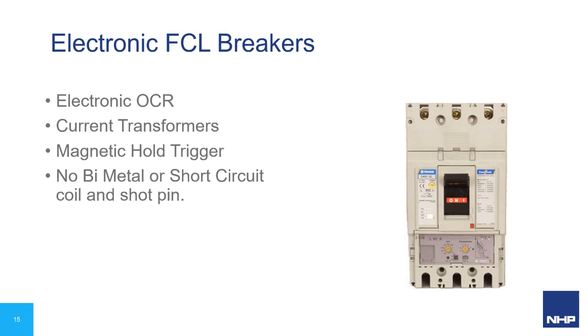according to the settings. So a sequential time period is a small gap in time which continually moves, so that the amount of energy that's scanned within that very, very tiny millisecond time envelope is calculated by the OCR, and it makes a decision. If it exceeds its settings, it will fire off its magnetic hold trigger to release the contacts. If it doesn't exceed it in that running time period, then the contacts will remain closed.